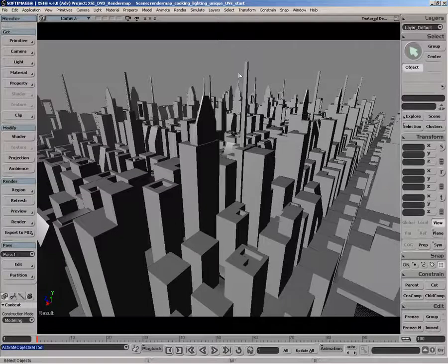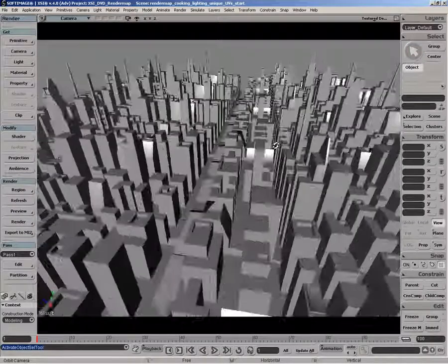And so the render mapping of it is a bit of a time-consuming process, because you need to create unique, non-overlapping UVs for the entire object. Doing that manually can be quite time-consuming. But what you can do is use the unique UV feature along with render map to basically automate the whole process. So a typical example would be a complex object.